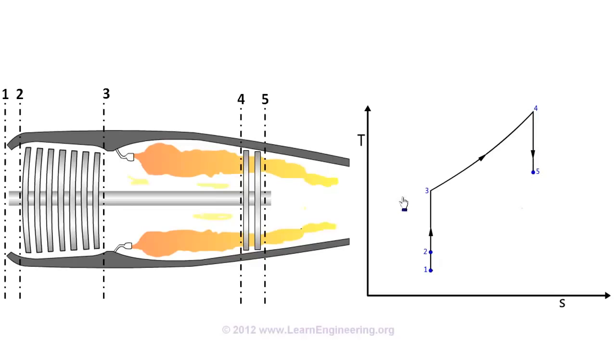The last section, which produces the high-velocity jet: the nozzle. This is again a constant entropy process, where internal energy of the fluid gets converted into kinetic energy. Here the pressure of the stream expands to the surrounding pressure. It should be noted here that the exit stream never goes back to the inlet condition. At inlet it sucks a fresh stream of air in. So this is an open cycle process. But since both these points have the same pressure, we can assume a pseudo-constant pressure process like this, in order to complete the cycle. This cycle is called a Brayton cycle.